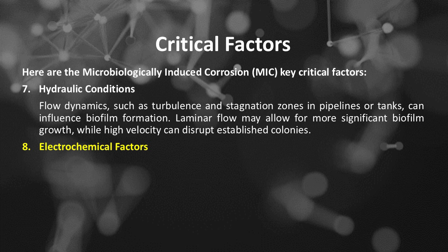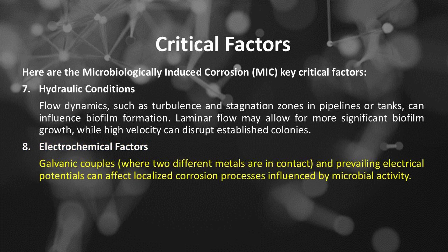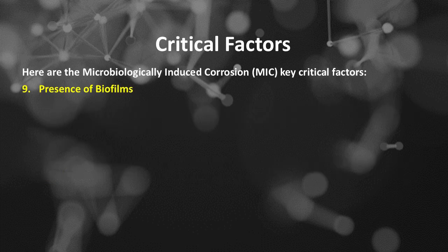Number 8 of the microbiologically induced corrosion, or MIC, key critical factors is electrochemical factors. Galvanic couples, where two different metals are in contact, and prevailing electrical potentials can affect localized corrosion processes influenced by microbial activity.